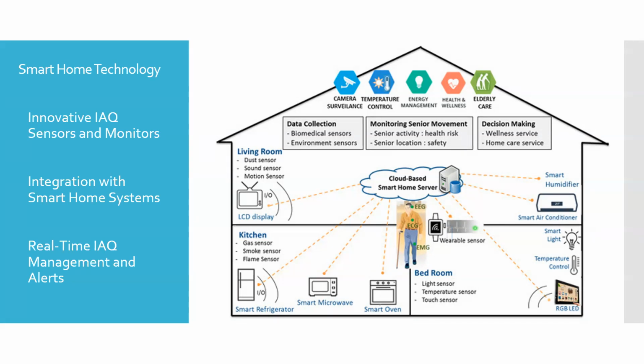and or possibly it will actually trigger a call for your HVAC technician. He may come knocking on your door and say, hey, we got a few alerts that said you have high humidity levels. I'm just here to check to make sure your system is functioning properly. And we're going to actually look at filters, make sure the filters aren't clogged, make sure the air handler is still running at its maximum efficiency. These things can offset some of that and actually lower the causes of having high humidity or contamination in the